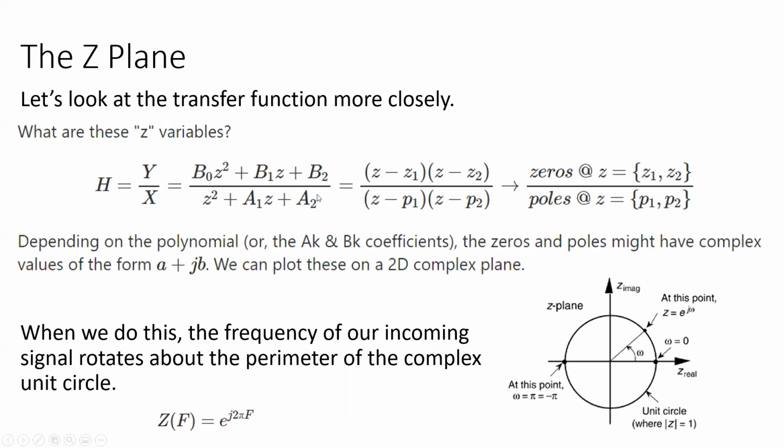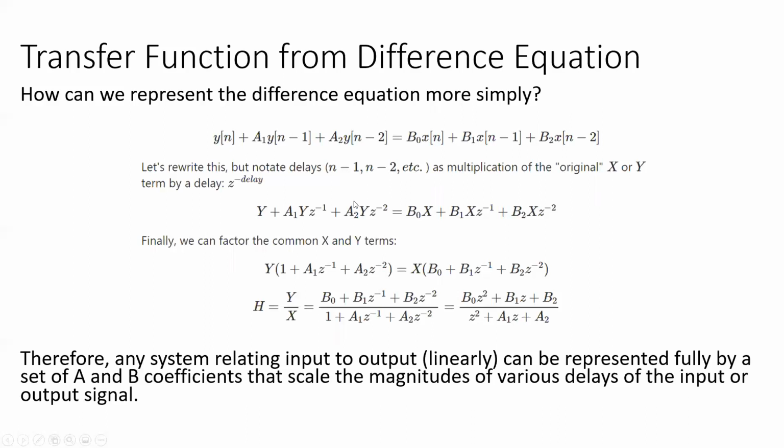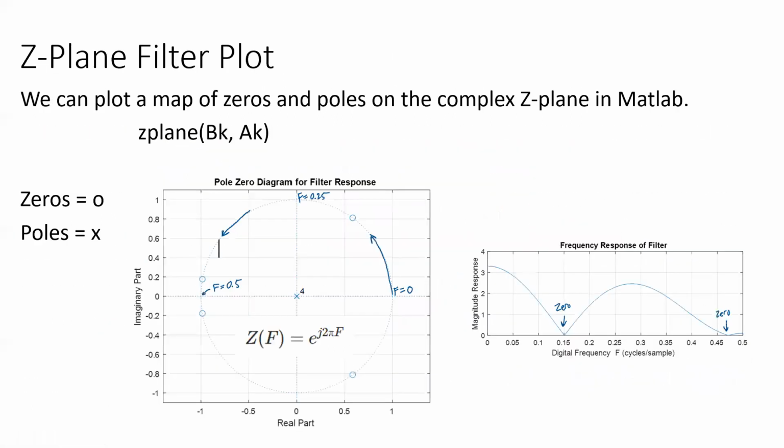Makes sense. And so you can work your way between any of these forms if you understand the relationship between them. So you can specify these and then just multiply it out. That'll get you your coefficients, and now you're back to a transfer function. If you want to go from a transfer function to the difference equation, multiply this over to the y, basically do the inverse of what we did before. Multiply this to the other side, multiply the x up top again. You end up with a y on one side and x's on the other. And then you can work your way backwards through here, and you'll eventually wind up at a difference equation. Cool. Okay. Sounds good.